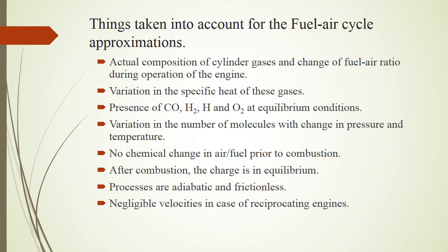The theoretical cycle that is based on the actual properties of the cylinder gases is called the fuel air cycle approximation, and that gives a better picture of performance to compare with the actual performance of the engine.